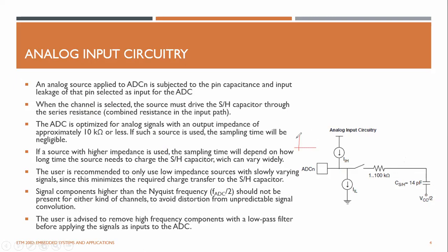So you need to charge this capacitor to some level. Like this is your signal, and this voltage here should be equal to this value in order to do the ADC, right? But there's a capacitor and resistor RC circuit, so there's a time lag. This is the original signal, but what appears here is behind, because it takes some time to charge this capacitor. So real fast signals cannot be processed. It depends on this resistance and this capacitance.